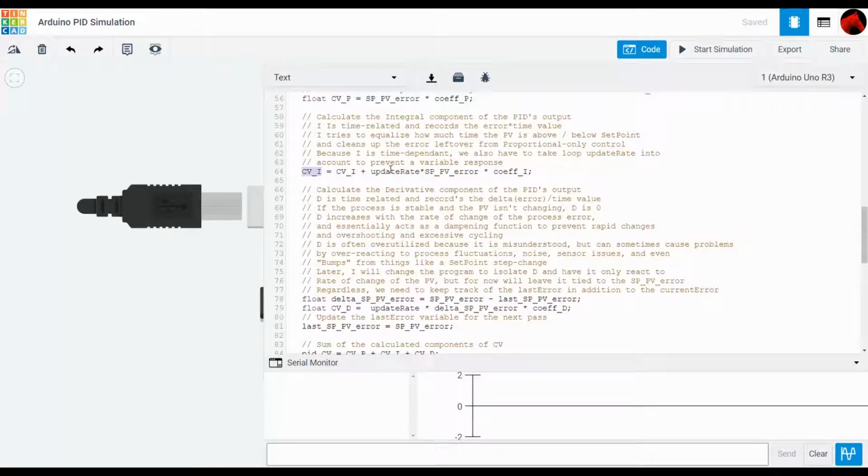And then if the process value still didn't change and the error was still 1 meter, then in second 2, there would be another 2 added to the integral. And little by little, the integral will increase and increase and increase, applying an offset to the output until that offset is high enough to start moving the process value towards the set point.